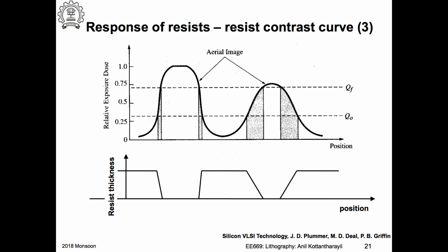So this is the re-entrant profile we are talking about, and the material will get deposited like this, because this is the... Okay, it will not get deposited under this cave, for example. Now there are other issues. So suppose I use this photoresist profile for masking something. I'm drawing on the two sides of the same photoresist profile, two shapes.